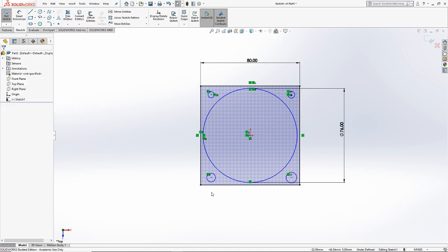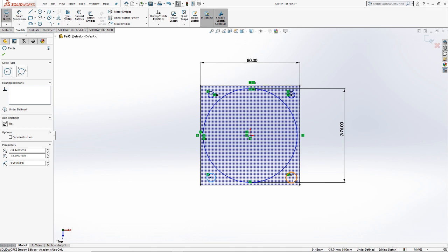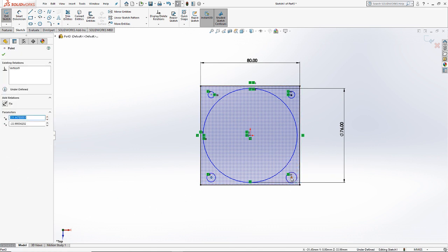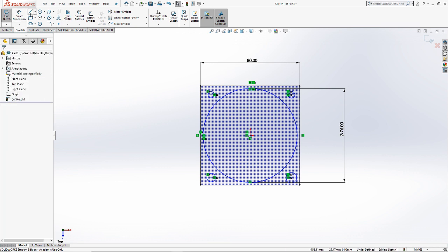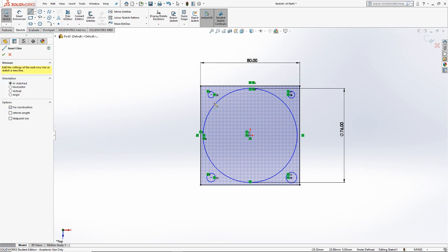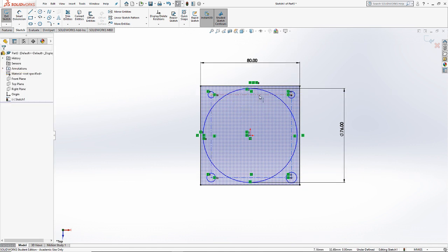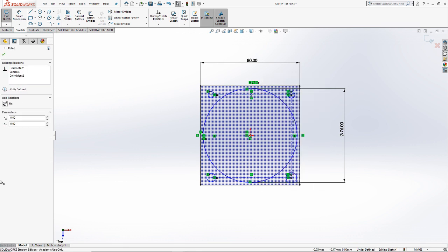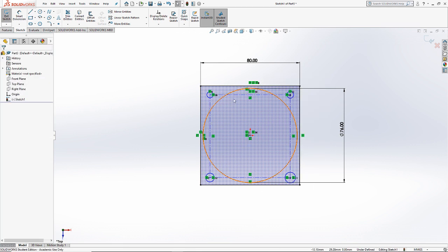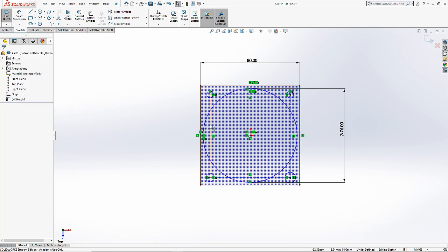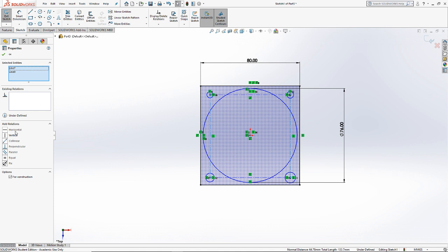These need to be vertical. These need to be horizontal. And I will point out that this type of situation could be made more or less convenient with some construction lines. For example, if I wanted to connect all these circles together, then I could do things like, hey, the midpoint of this line needs to be vertically aligned to the origin, or I could say these two lines need to be horizontal instead of having to center click all those circles and apply relations.